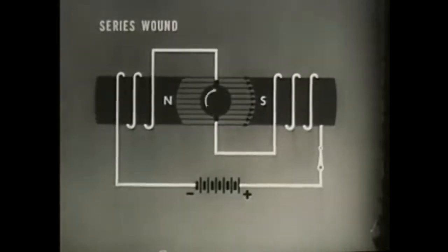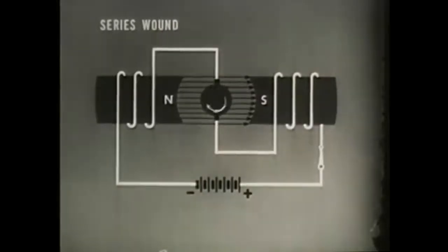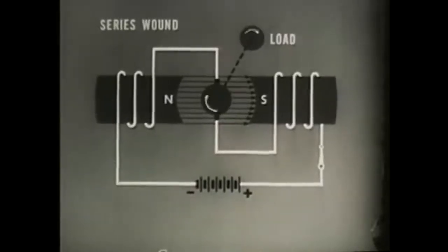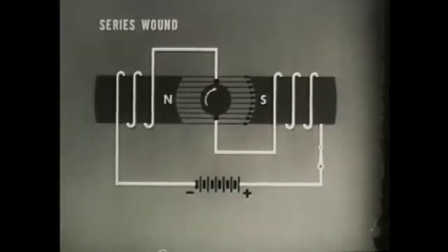The motor begins to turn, attempting to develop enough CEMF to completely oppose the applied EMF. The load prevents this, acting to control the speed of the motor. But if the load is suddenly removed, like in the case of a broken belt, the motor will build up speed, trying to develop more CEMF until it destroys itself.